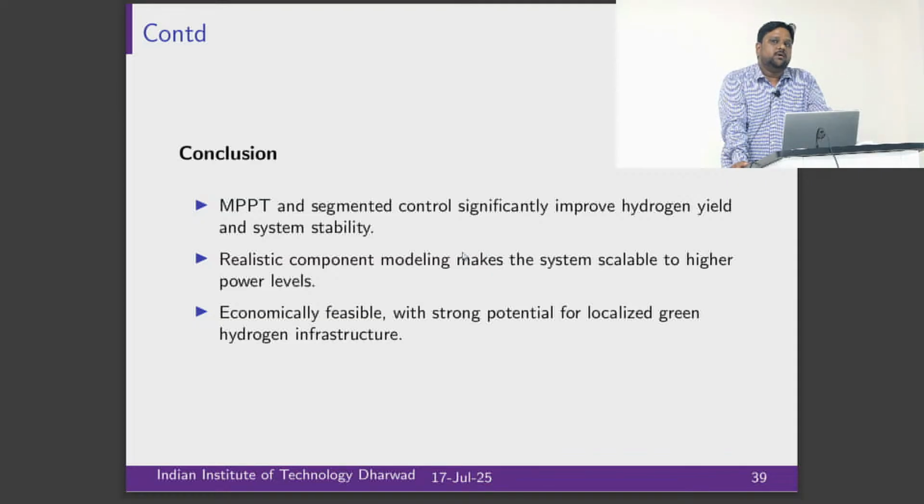But of course, its counterpart is called a fuel cell. The hydrogen that you produce, you can inject back to the grid through a fuel cell, where you give hydrogen as an input. Then it is exactly the opposite operation. And there are certain technologies available which we call the reversible electrolyzer, where you can do both electrolysis and fuel cell operation in a single cell. But here, of course, the grid ancillary service I mentioned refers to the flexible load, meaning the sink of active power. That's how you can give some service to the grid.